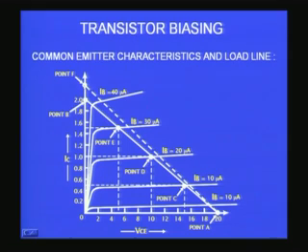Therefore you will be at a new point along the graph, which is here, corresponding to 2.2 milliamperes. So, the moment I have this point and this point, I can join them by a line, here shown by a dotted line, and this corresponds to a new load line because the load is changed. You have changed the load from 10K to 9K, therefore you are obtaining a new line, right.